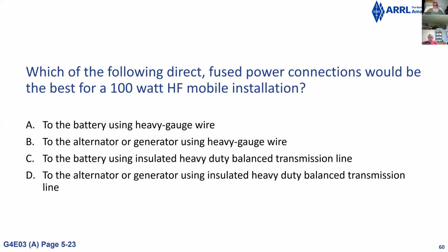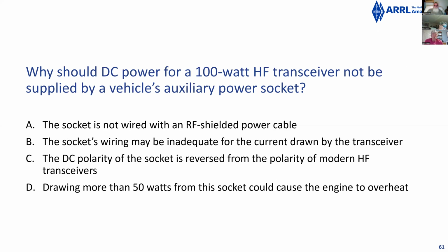It allows noise to pass more easily. It doesn't reject noise as much. Yeah, twisted pair Ethernet works that way, as Chris is saying. That the twisting, and also being a balanced pair with equal and opposite signals on the two wires, those prevent picking up induced voltages.